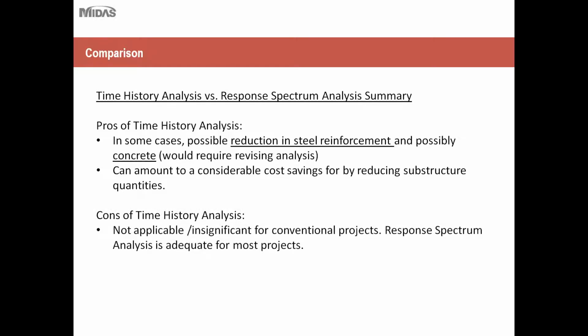First, it's not applicable or it's insignificant for conventional projects. So for those of you who are working in low seismic regions, very rarely will you ever need to use time history analysis, if at all. So for the most part, you'll be sticking to response spectrum analysis because it's not as optimal, but it requires much less effort and it's adequate for most conventional projects.